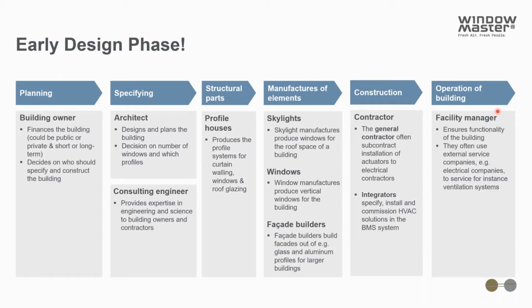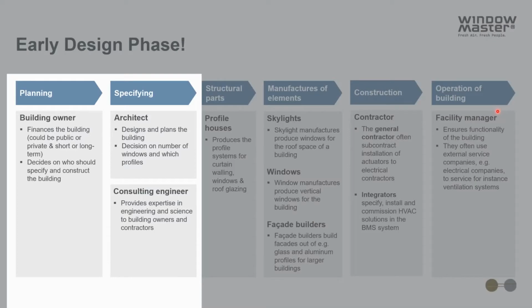And this is really unfortunate because the building has such a huge impact on the overall success of a natural ventilation system. So what we want to emphasize today is also really to think about natural ventilation in the early design phase, like you would also, for example, with daylighting. The overall building design impacts this type of system in a huge way. So we want to emphasize that natural ventilation is something to think of in the early design phase.